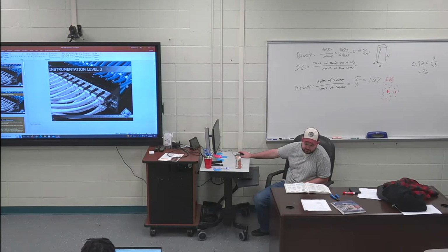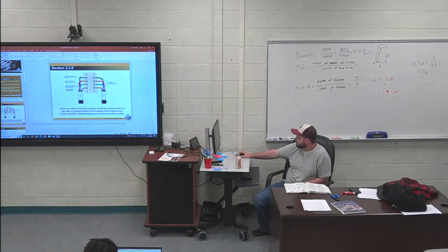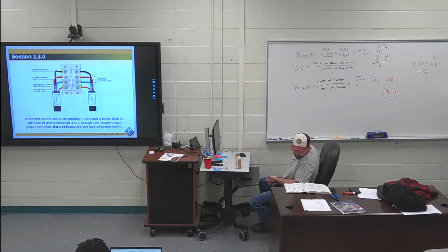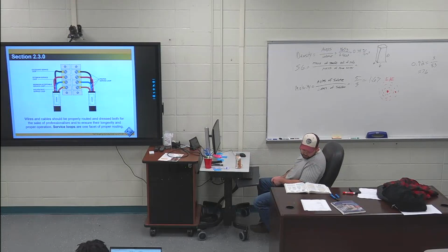Cable conductor routing and inspection considerations. The first bullet point on page 33 is highlighted. The procedures for cable conductor routing and inspection include the following considerations. First bullet point is wire bends. For UTP and STP cable routing, use a minimum bending radius of 4 times the outside diameter of the wire or cable, unless otherwise specified by the cable manufacturer.